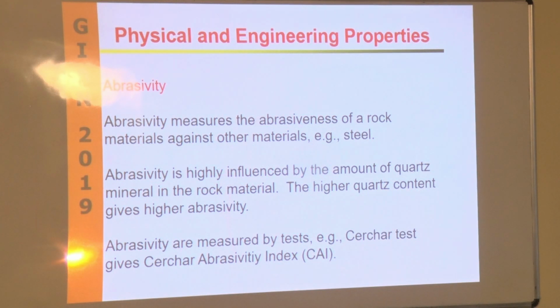That will tell you what type of steel or material you need to use for your tools. From a cost and operational point of view, this is extremely important, because it tells you how often you need to stop the machine, a TBM for example, a tunnel boring machine, to replace the cutters. That is a big cost, and it is one of the parameters that goes into the design and commissioning of the machine. If you make a mistake there, you are going to pay for it for the entire cost of the project. Big mining machinery too. Yeah, surface miners, continuous miners.